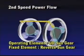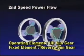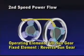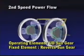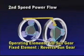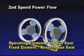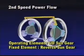Since the reverse sun gear is fixed by the second brake, driving force from the output annulus gear rotates the overdrive planetary carrier to the right direction, as the overdrive pinion idles around the reverse sun gear.